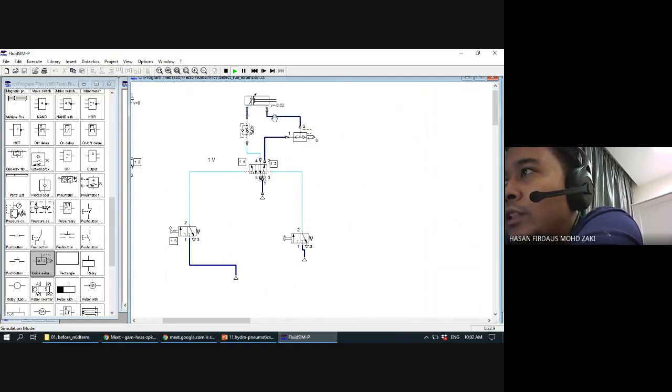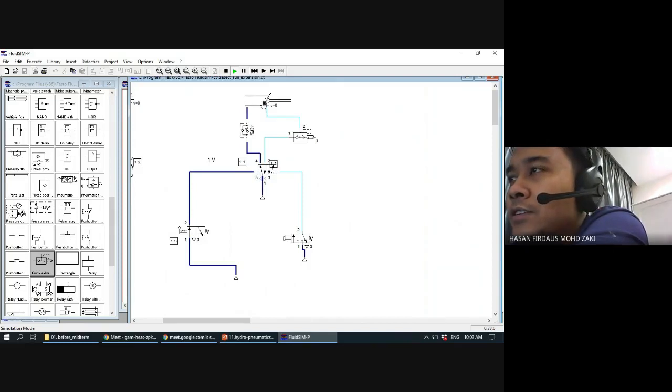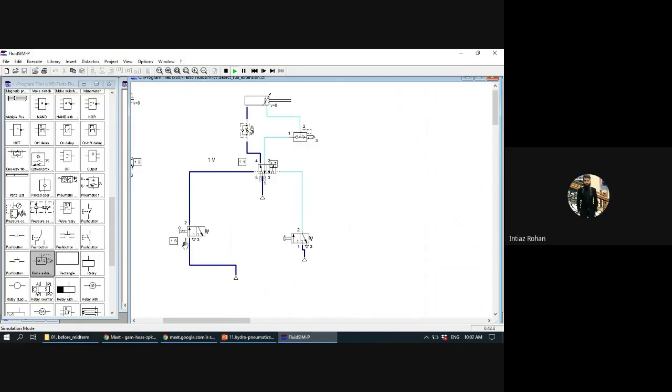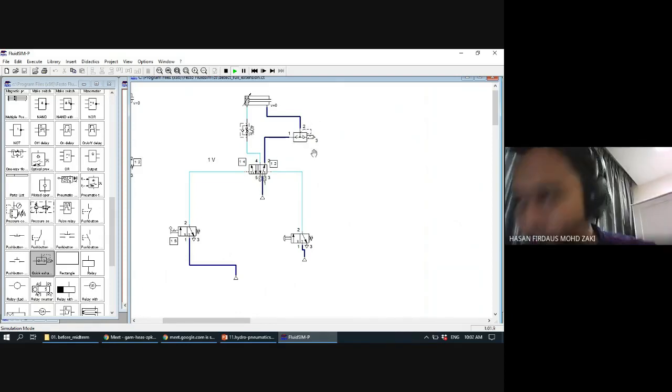So this one will take place when this one is in advance, so this one will go very fast in the advanced position. Yeah, I can visualize it now. The opposite one is basically to make it slower, and this one is to make it quicker, right? Yep. This one-way flow valve you can use to control the speed. This one you can go in full speed.